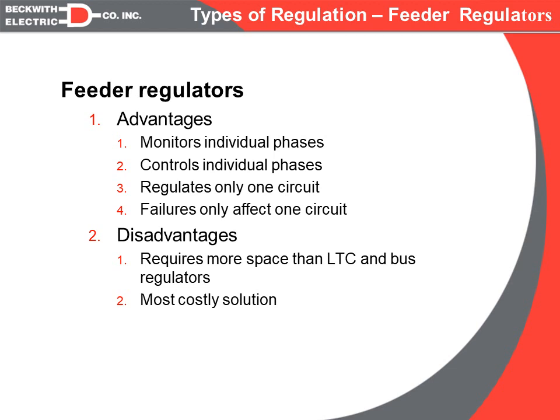So the advantages of regulators are they provide you the most flexibility in controlling the voltage, because now each regulator is zoned to control only one phase of one circuit. So from the LTC, it is zoned all three phases of all four circuits. Single phase bus regulators have three zones: same phase, but on all four circuits.